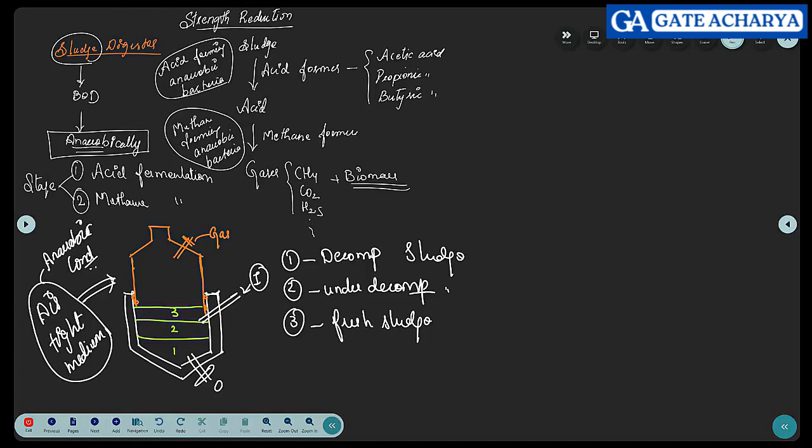A part is available below the ground level, and the balance part of the structure is above the ground level. Below the ground level, it is a CC structure. Above the ground level, it is a steel drum. This drum keeps moving up and down. Why does it move up and down? Whenever there is more gas, it moves up. Whenever the gas is less, it moves down.